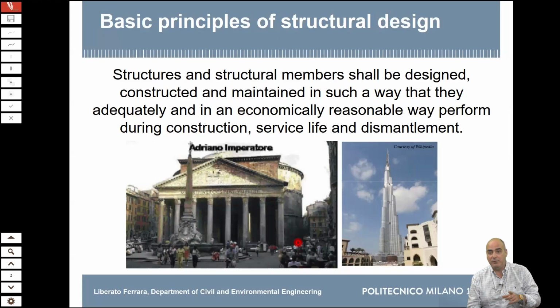The other thing that you have to take into account when they speak about durability of Roman concrete is: how is the stress level in this structure? You have a 2 meter thick wall just supporting itself. What you can expect is really a few megapascal of stress. Then the structure has no reinforcement and it's in an urban area. There is some traffic, but not that much. The sea is about 30 kilometers away, so it's difficult for other aggressive agents to arrive. So really, this structure is in a protected condition.